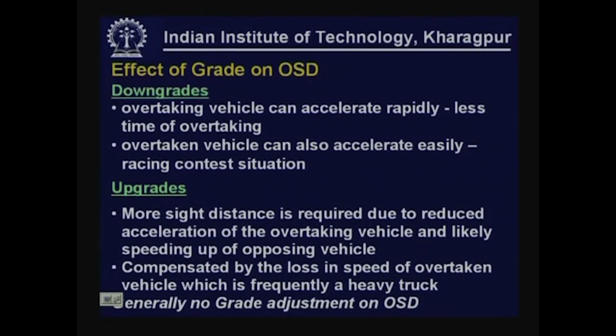Similarly, for upgrades, more sight distance is required due to reduced acceleration of the overtaking vehicle and likely speeding up of opposing vehicles.